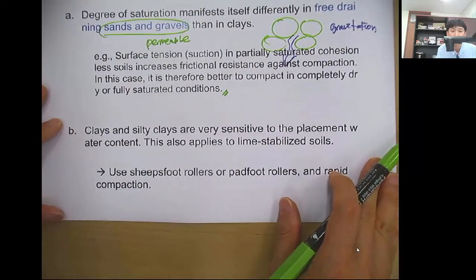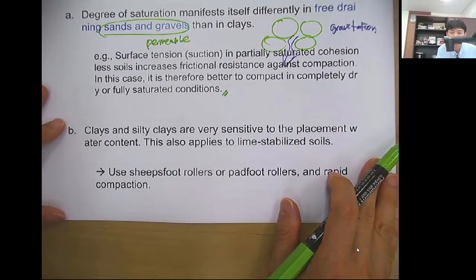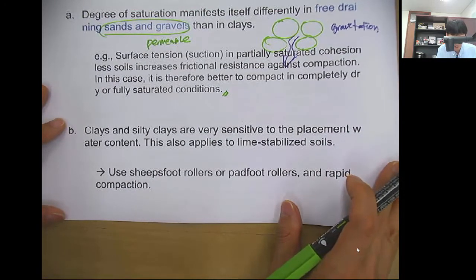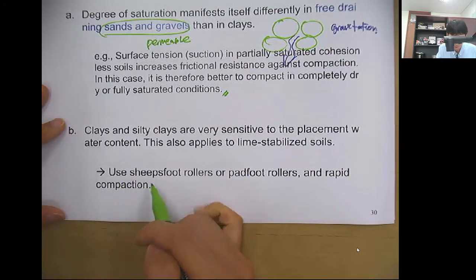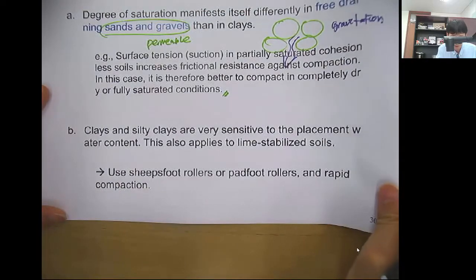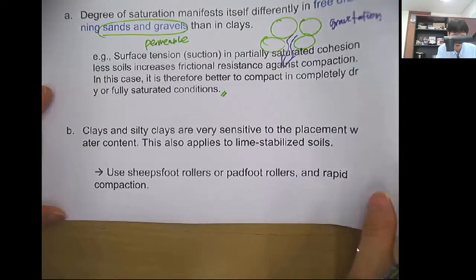And clays and silty clays are very sensitive to the placement water content. And this also applies to lime stabilized soil. In this case, use a sheepsfoot roller or a padfoot roller and just do the compaction very fast, rapid compaction.